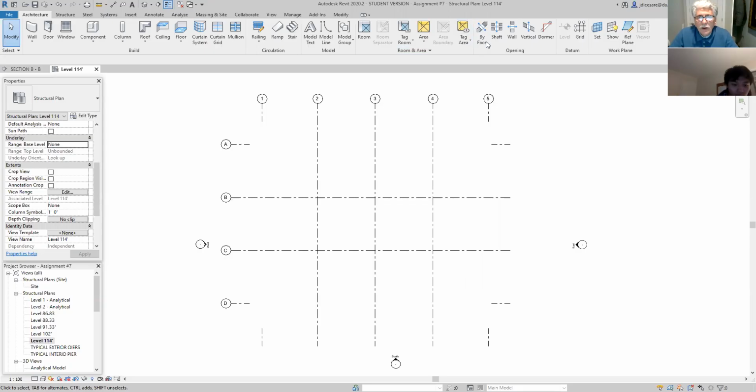So we all see that. Okay, so now the first thing I want to do here is adjust all these grid lines, because you know that with steel structures, you don't want the grid lines to be underneath your structure so that you can be clear. So the first thing I want to do is adjust all these grid lines with a gap.